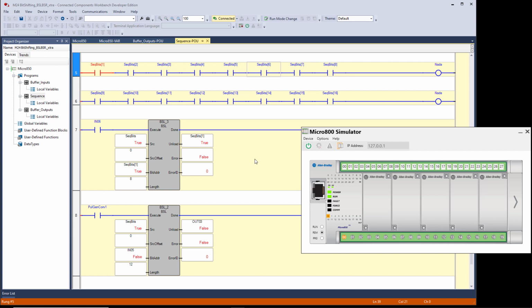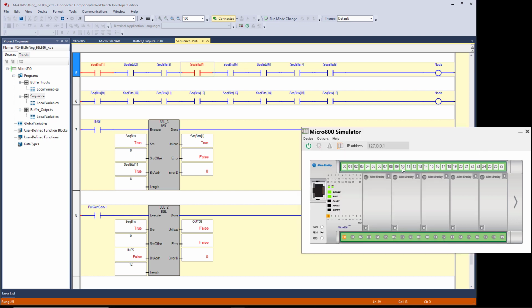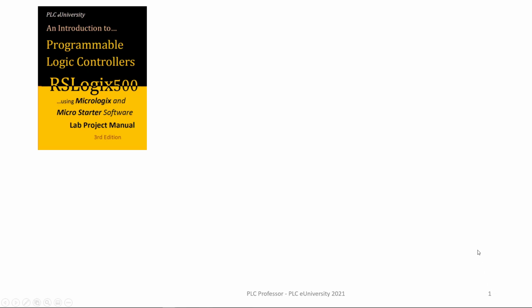So if you had a rotary index table with 8 stations and you did a certain function or procedure at station 4, when that logic is complete, then it would turn on that bit. And then when you rotate the table, that part now moves from 4 to 5 and so forth. Now you can do this with bit shift right. So we could set up a bit shift right. If you reverse the direction of the rotary index table, it would reverse the direction of the recirculating bits.